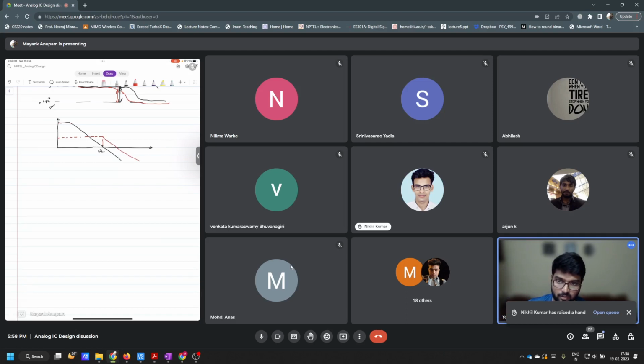Okay, and this was actually explained very well in the lectures also. So that is why I didn't touch this part, because there is not much to discuss here in this concept. The closed loop system is basically behaving like an ideal system till the open loop unity gain frequency of the loop gain plot, and after that it starts going down. Its response starts going down, basically omega_u of the loop is the pole for the closed loop system.